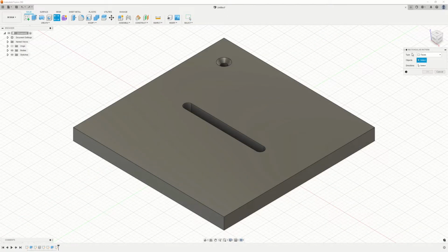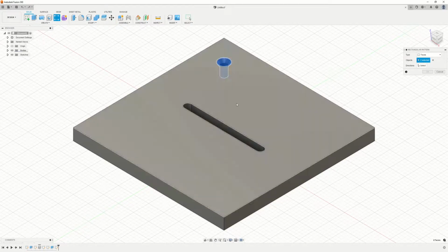Moving down in the rectangular pattern command window, we have our object selection filter. This allows us to pick up various objects like faces, bodies, features, and components like we've previously seen. It's pre-selected, and I know that because the box is filled with color blue. And if it's not, so let's say if we were working with the directions filter, but now we want to either select additional objects or deselect objects and reselect some, we can click on that select box there. It populates with the color blue. Now we're all set to pick up whatever we want to replicate.